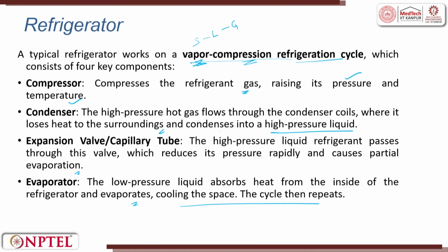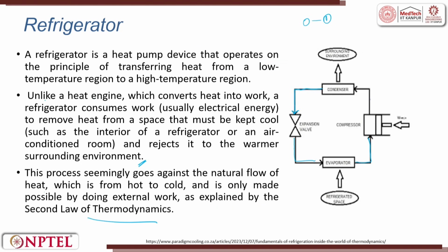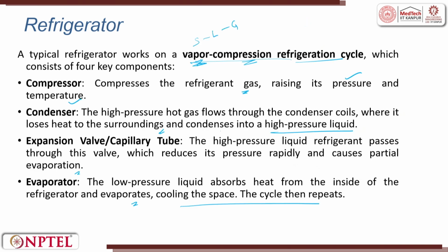So, in a crude sense, a refrigerator is different from heat engines. Unlike heat engines, which convert heat into work, a refrigerator consumes work to remove heat from the space that must be kept cold and rejects it to the warmer surrounding environment.